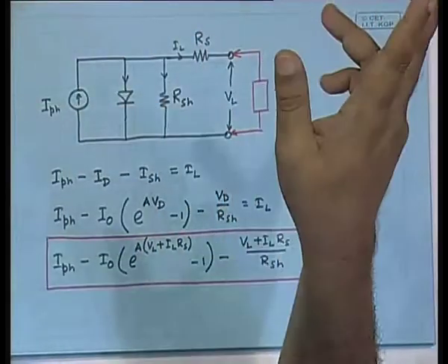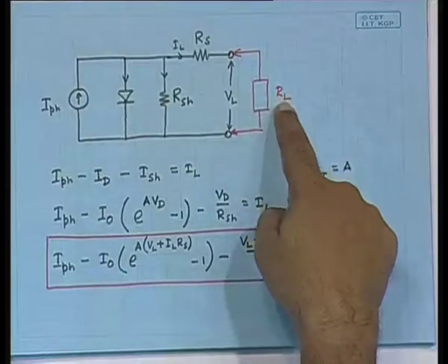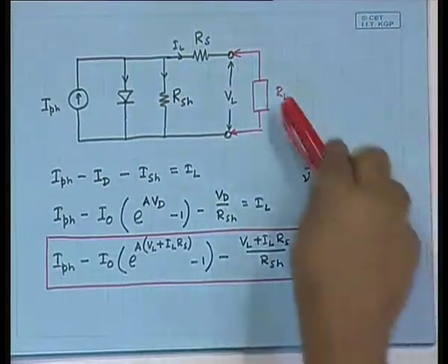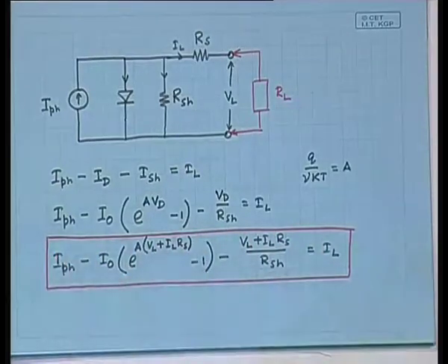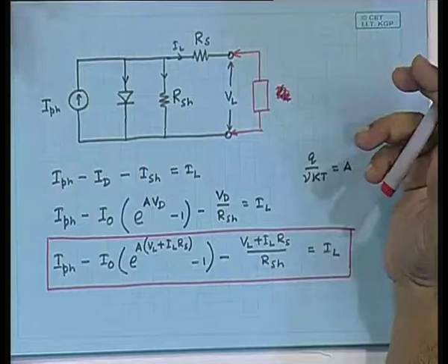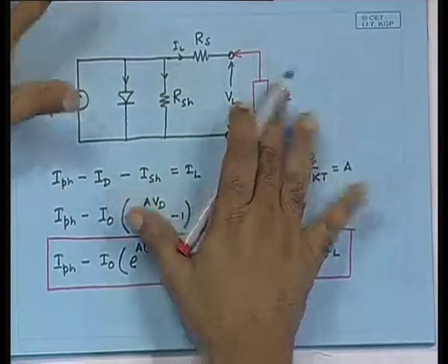Yes. So, both V_L and R_L have a linear relationship, V_L and I_L. So, because it is a current I_L which is passing through the resistance R_L. No, it will not have. Wait a minute. The I_L that is passing through this resistance R, after all it is coming through here. That idea is true for voltage sources. Here it is not quite so. This load, what is it? Is it a resistance? Is it a motor? I said that it could be anything. That is why even though I have written R_L, it does not appear here. You could as well simply ignore this R_L and assume that it is some kind of load. There is no reason to assume that it is a specific resistance load. So, it does not really appear, it could be any load.